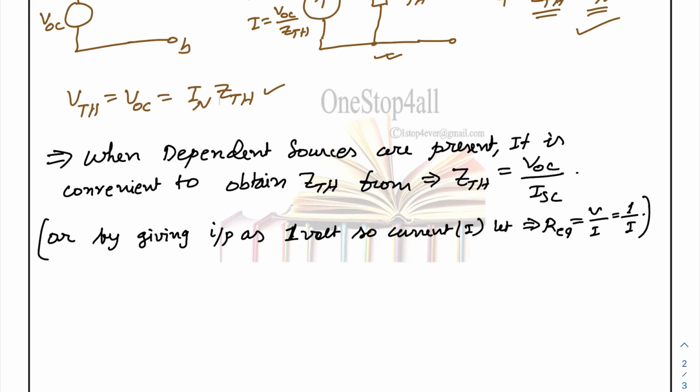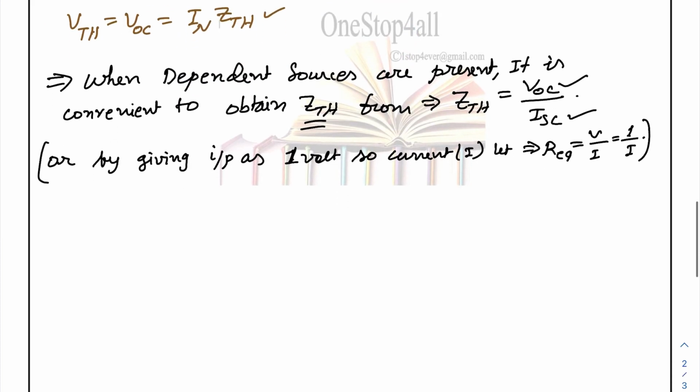आसानी से हम लोग ये रेजिस्टेंस, मीन्स इम्पीडेंस, जो थेवेनिन या फिर नॉर्टन इक्विवेलेंट इम्पीडेंस होगा, वो आसानी से कैलकुलेट कर सकते हैं, ठीक है। समझ में आया ना, डिपेंडेंट सोर्स के लिए, क्योंकि डिपेंडेंट सोर्स को हमको कुछ करना ही नहीं, उसको चेंज नहीं करना है। तो आप बताइए प्रैक्टिकल सर्किट में ZTH जो ऑब्टेन करते हैं, वो हम लोग कैसे ऑब्टेन करते हैं? बाय ओपन सर्किट वोल्टेज एंड शॉर्ट सर्किट करंट। ये दोनों की हेल्प से हम Z, मीन्स इक्विवेलेंट थेवेनिन इम्पीडेंस या नॉर्टन इक्विवेलेंट इम्पीडेंस निकाल लेते हैं। Now it's time to go for some numericals.